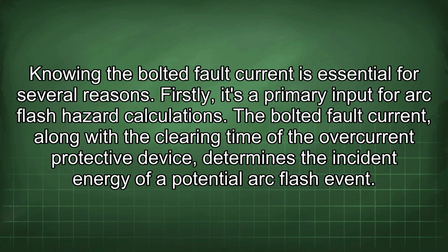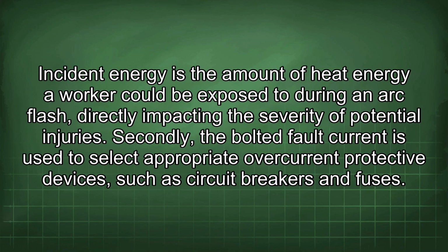Knowing the bolted fault current is essential for several reasons. Firstly, it's a primary input for arc flash hazard calculations. The bolted fault current, along with the clearing time of the overcurrent protective device, determines the incident energy of a potential arc flash event. Incident energy is the amount of heat energy a worker could be exposed to during an arc flash, directly impacting the severity of potential injuries.